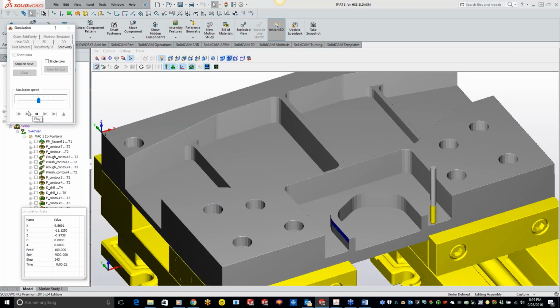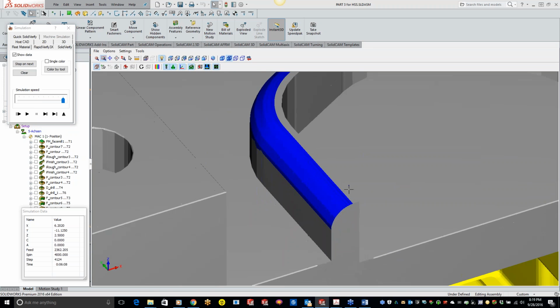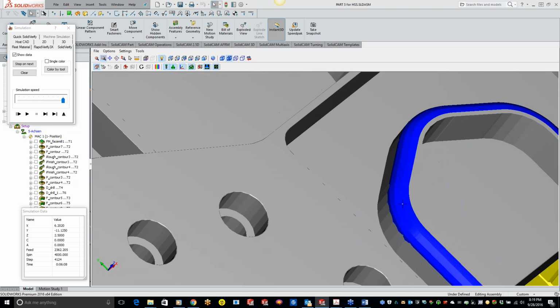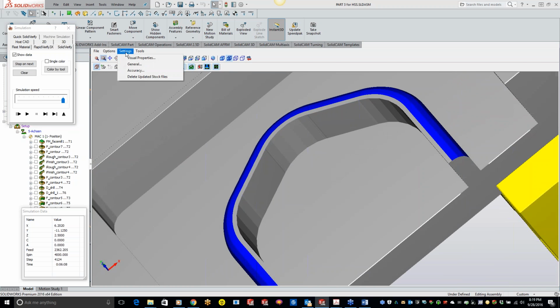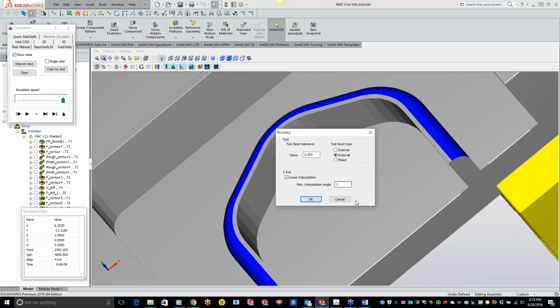And now I'm taking a nice light cut, working myself into the cut there, just going back and forth. And speed it up here. And like I said, I set the tolerance, or the step over, pretty small in here, so we should have a real nice finish in there. So you see a nice surface in there. And I don't have my surface quality or my accuracy set real high right now.